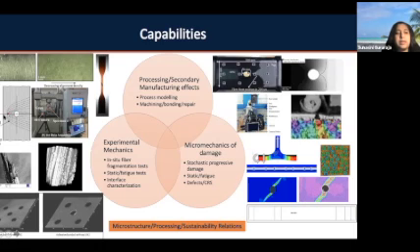Besides this, we have also done microstructural improvements, aligning CNTs, for example, using non-uniform electric fields to improve the strength of these materials. These are GFRP materials, and we used multiple electrodes to span a larger area, so that this kind of process can be used for an actual structure. Those are the kinds of studies that we have done. And there is a bunch of experimental mechanics based studies looking at in situ property measurements as well, that is of interest to our group too.